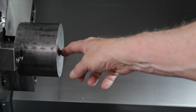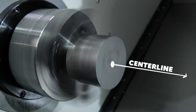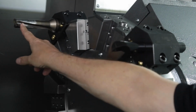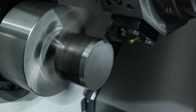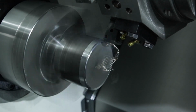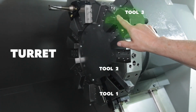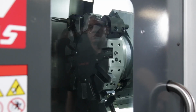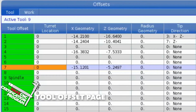But with a CNC lathe, the center line of spindle rotation does not move relative to the X-axis, so there's not much need for an X-axis work offset. The cutting tools are clamped in the turret here. The workpiece rotates with the spindle here, but otherwise doesn't move inside the machine. The turret holding the cutting tools does move inside the machine. We need to tell the machine where each cutting tool is compared to our workpiece. We do this using the tool offset page.